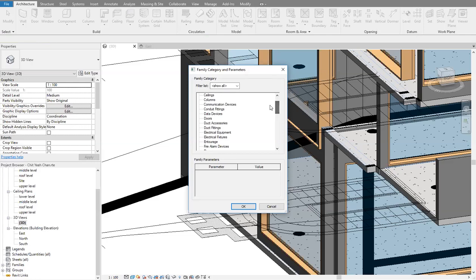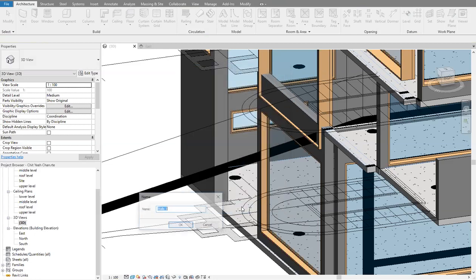For example, if I'm planning to model a door, I have to select door, because anything in your model in Revit should be under one category. Of course, a chimney is not a door. As you can see, there are many types of things, but basically I will just select wall. I will consider it as a wall because there is no category called ceiling. So wall is the closest thing for this element. So I created wall, and then I will call it chimney.